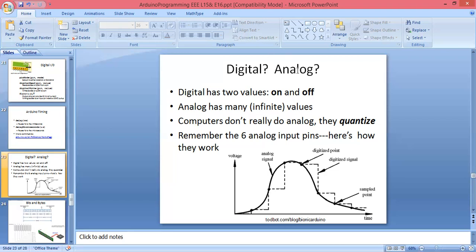So analog से digital में क्या किया था हमने? We are converting analog value into digital. The same only in the opposite process. We have to convert that digital value into the analog. If we are having 0 to 255 digital value, then in analog you will get 0 to 5 volt. So digital values are nothing but 0 and 1. 1 means on and 0 means off. And analog will have infinite values.